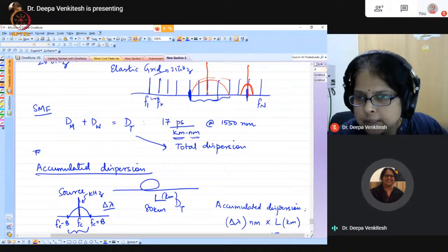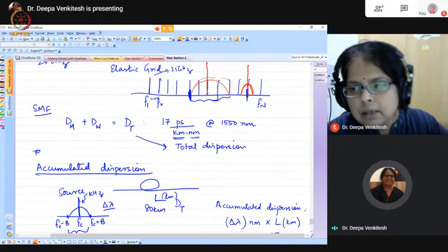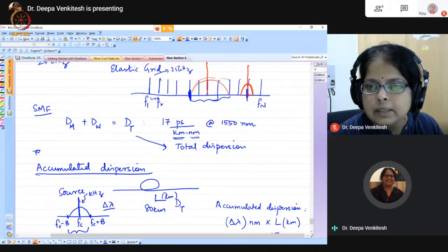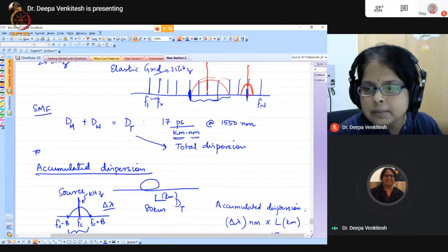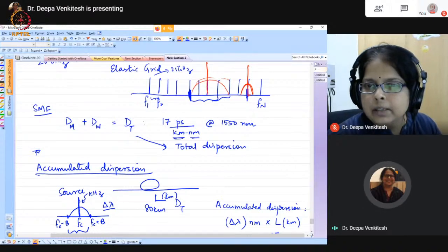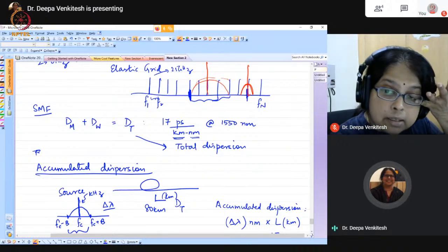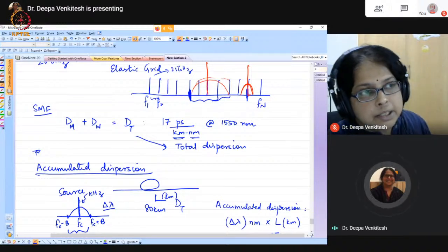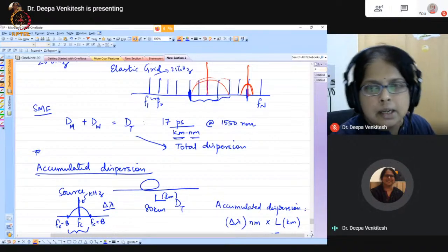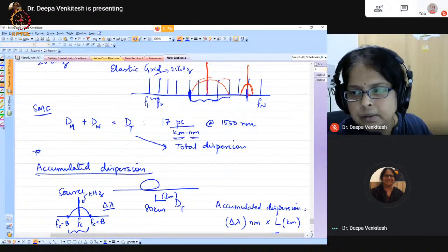What should the laser's polarization extinction be? Yeah, so that's what I said at the transmitter. Polarization extinction of greater than 20 dB is fine for a polarization multiplexed transmission system. Typically, lasers come with polarization extinction of 30 dB or so. That should be the number that you need to target. But more than the laser, you are using modulators, so the constraint comes from the polarization extinction of the modulator rather than the laser. Lasers typically come with larger polarization extinctions.